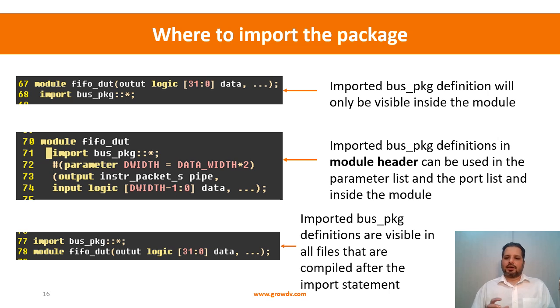Packages can be imported anywhere that is legal for their content. As we have talked about, even the tick include can be done anywhere where it is legal for the content that you are importing. But let's look at some of the places and how it affects visibility. You can import a package within a module. When I have a complete module declaration and then import a particular package, this imported package definition will only be visible within the module. Inside the module only this will be visible.